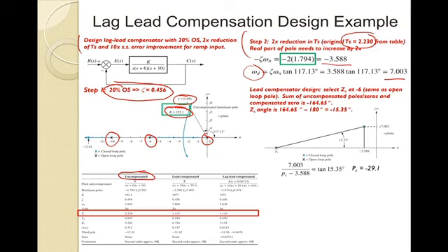So next, once we have the original open loop poles, and there were no zeros, but the original open loop poles, and we have this new location for our compensator, we can now pick our compensator 0. Why? Because we know that the sum of those angles, everything has to add up to 180. Here, when we do the calculations, we're about minus 164.